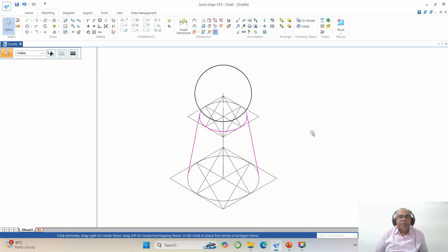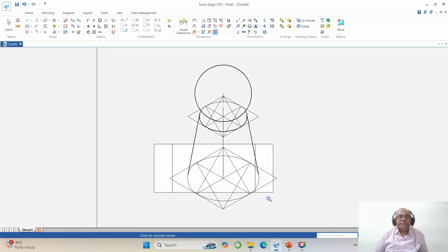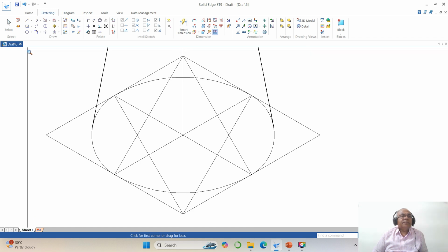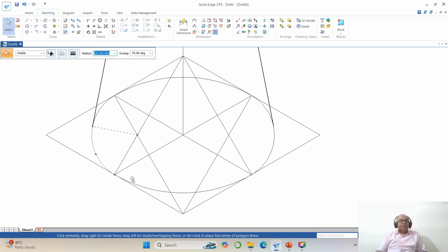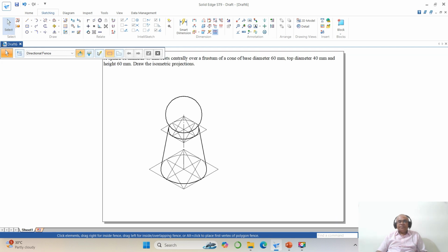Okay. Now you come down to this. Okay. Then go to split this line arc till here, which is this end point. Okay. Then split this line to this end point. Now you go to select this and select this, make it 0.5. Okay, select this line and you make this as the axis line. So now you go to fit. Okay, now we have the entire drawing.